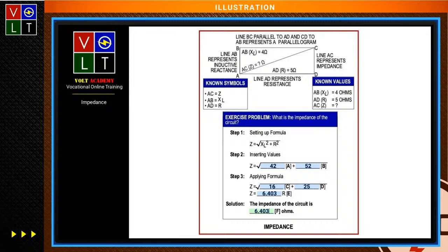So when I'm looking at the AC circuit, capacitive reactance and inductive reactance must be considered before the total impedance in a circuit can be found. And that's why I was showing how you do that. Even though we give you known values when we're doing illustrations, this is how you get to those known values, knowing what's in the circuit in order to determine what that impedance is for those added together, so you can divide that into the voltage to determine what the amperage is. Yeah, and like I say, there is no question that's stupid at NEC for Dummies.